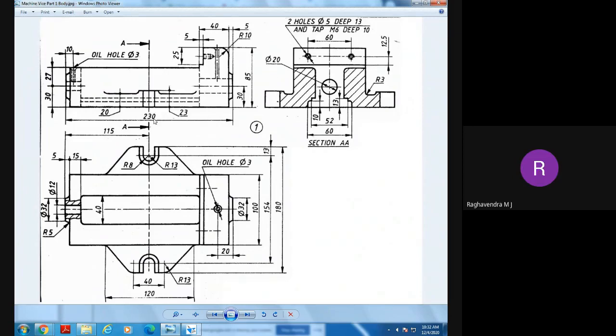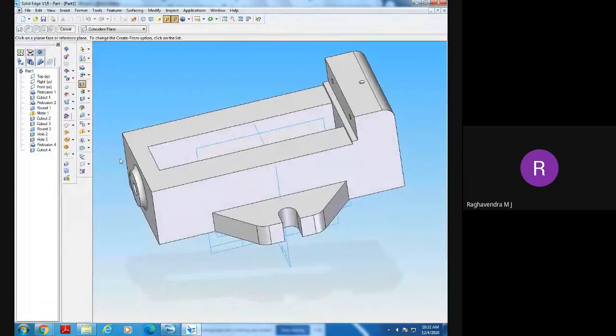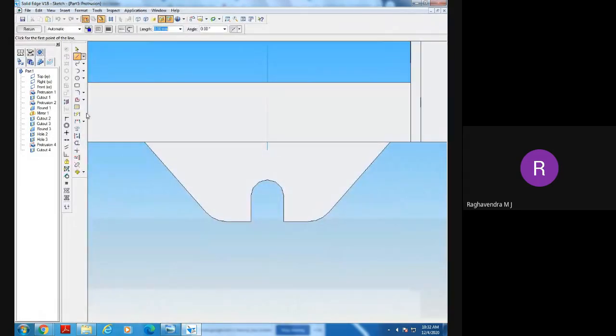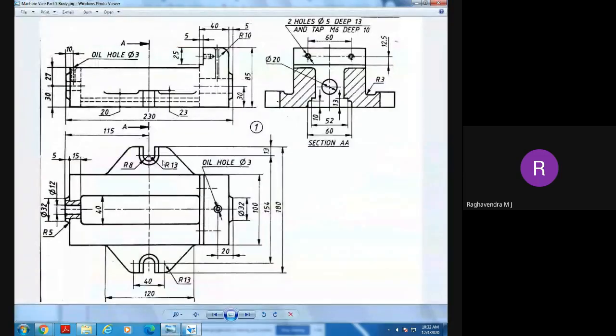3 millimeters, sir. Therefore, from this top surface, he has done some small protrusion of 3 millimeters. From where? From this top surface. Go to the protrusion option and select this top surface. Now he has done a small protrusion of 3 millimeters thickness, and what is the width?